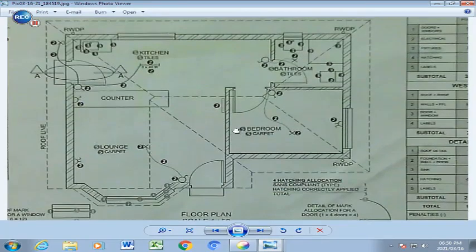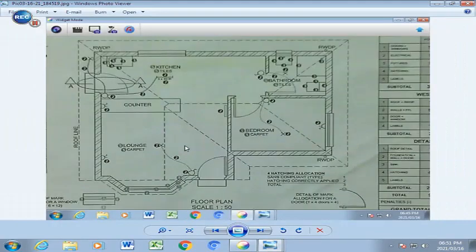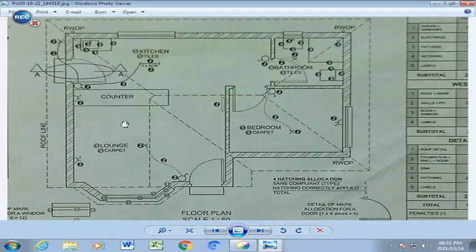And then you need to hatch the entire wall unit inside and outside, same hatching, 2 lines gap, and you finish this off with having the labels, kitchen, and what the floor finish should be, tiles, carpet, etc., and so on. Okay, that concludes the evaluation of your floor plan.